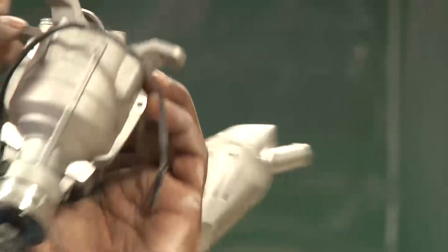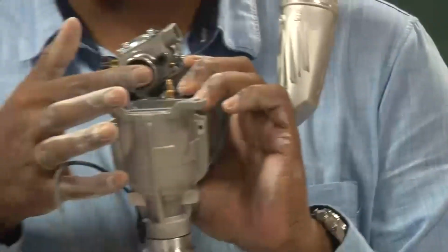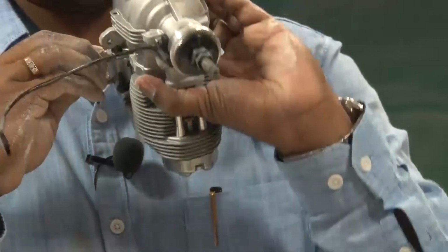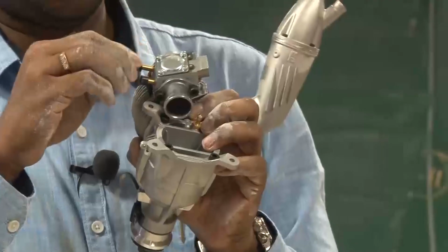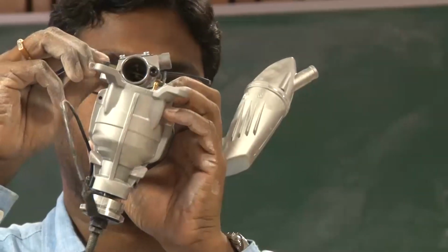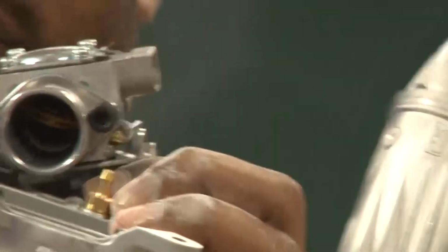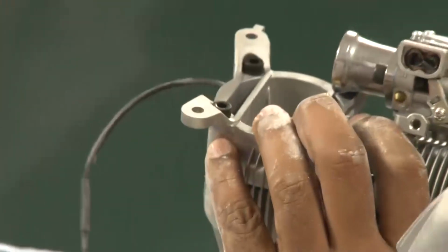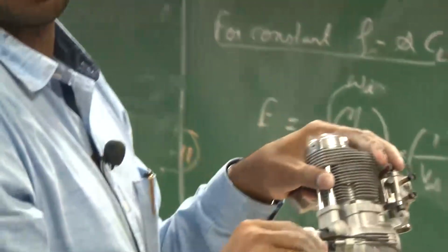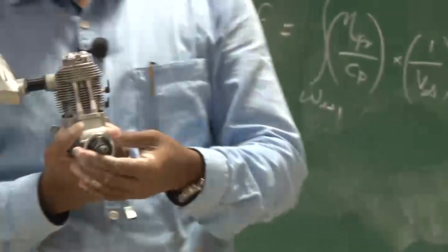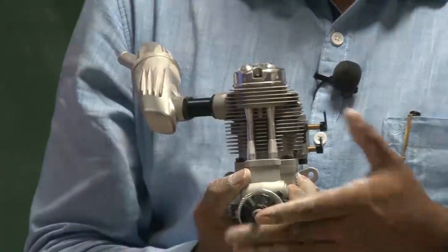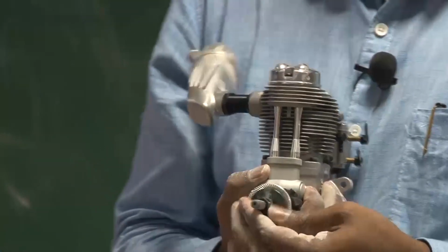This is like a lid for this fuel air mixture, it acts like a lid to this mouth, and you can see there is a valve that will be rotating as I rotate this lever. So it controls the fuel air mixture and so the RPM of this shaft. Once you mount the propeller here, you will be able to convert this available mechanical shaft power to the useful power.